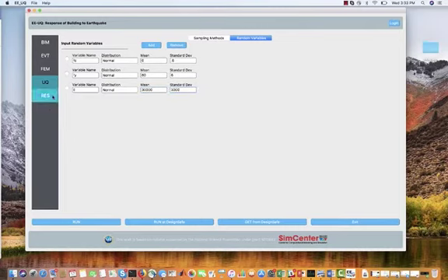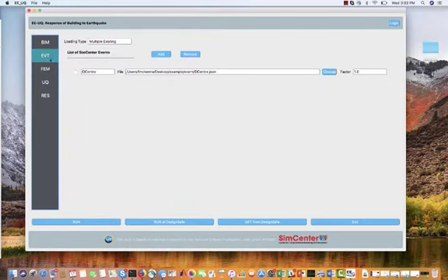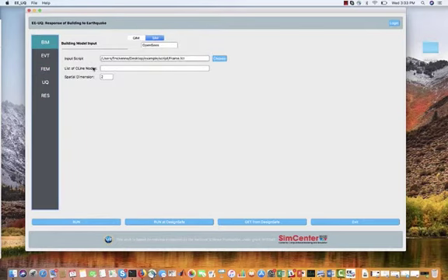So now I'm almost ready to run. Back in the BIM file, there is this list of C-line nodes. I didn't provide any information. This program will automatically record the maximum acceleration, displacements, and interstory drifts for a bunch of nodes. You have to specify what those nodes are when you use OpenSees.